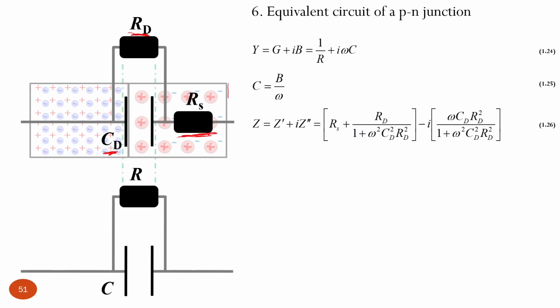Plus, we have some electrical contacts to these devices, and these electrical contacts at the interfaces can also provide some additional resistance. It depends on the quality of the electrical contact. It can be very small or it can be quite significant. So in total, instead of the ideal case, we have in addition this series resistance.